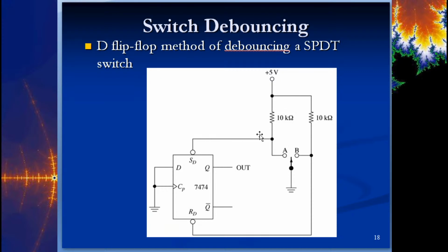So that's one condition. Then if you move it over to A, exactly the opposite happens. Now there's no way to drop that 5 volts across the 10K, and so this entire thing is all 5 volts because it's just one big conductor. However, now you can drop the 5 volts across this 10K, and you have a ground over here that you can get to, to let the current get to ground. So now this side would have the 0, and this side would have the 1. So it's just going to flip back and forth based on where this switch is.